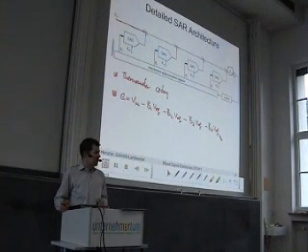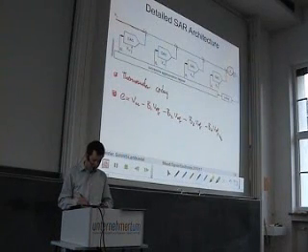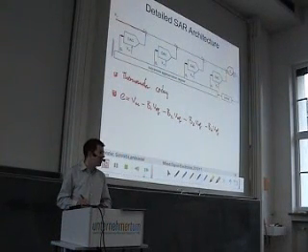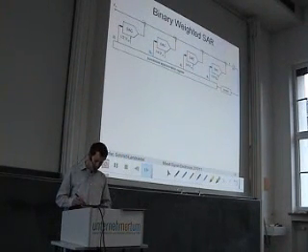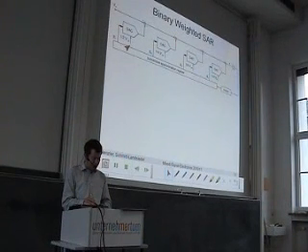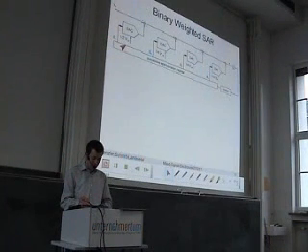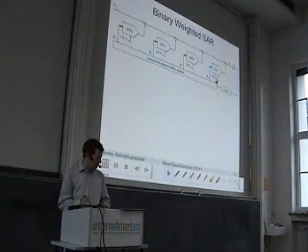For a binary search technique, and from an effort perspective, it is advantageous to use not equal DACs, but to use binary weighted DACs. So this means we have one DAC that we use for the first iteration cycle. We have here 1/2 times Vref. For the next cycle, we use 1/4 Vref as the reference voltage, then 1/8 Vref, 1/16 Vref.